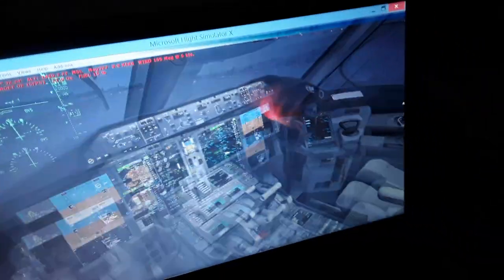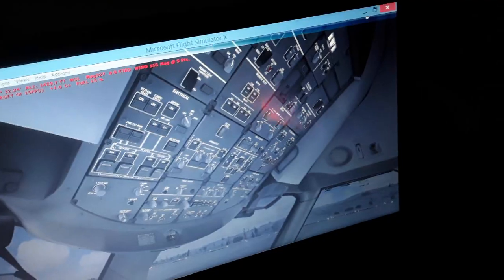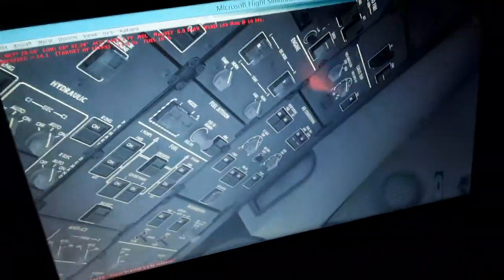One is for operating the gearbox, with channel redundancy. One channel fails, the other takes over. Controls, monitors, and displays all the engine data using the EICAS. Also the pressurization from the left and the right engine, we need for cabin pressurization, engine anti-ice, air conditioning, ventilation. The hydraulic fluid tanks, all the systems use hydraulic pressure, like the flight controls, landing gear, extended track, thrust reversers, flaps, slats, speed brakes, the elevator, aileron, spoilers, flaps, and also the parking brakes. They use hydraulic pressure from the engines.